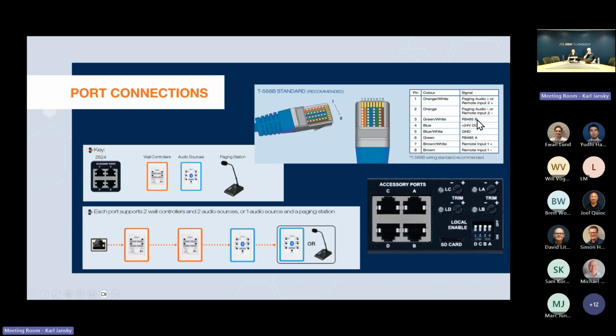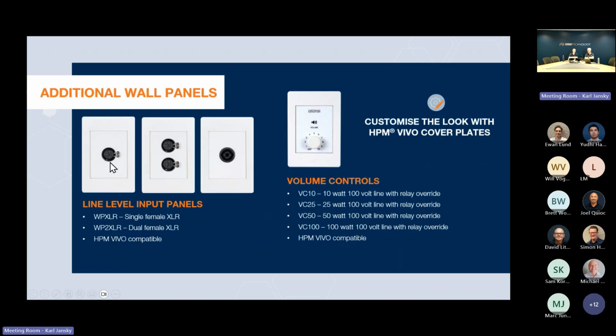And because these, I didn't say before, I'm sorry, the remote inputs on this connector are standard balanced audio. So it does allow you, if you want to use any other form of audio input source, a balanced audio input source at line level, you can send it in through these accessory ports. And as an example, we have some input wall plates that show you monitor cells, and you could connect this in a remote zone and send balanced audio back into the system.